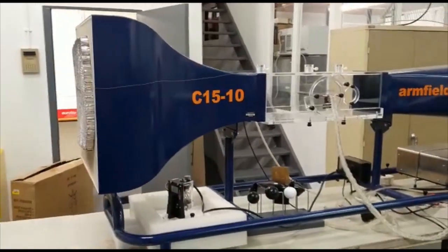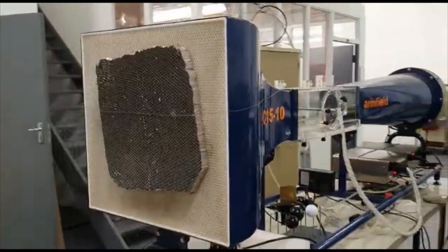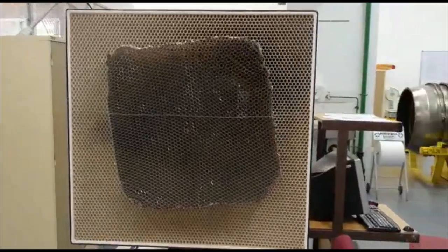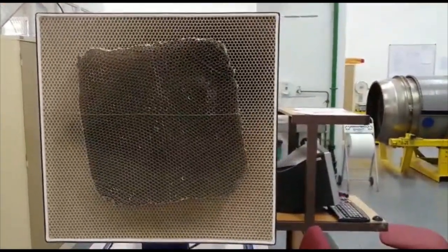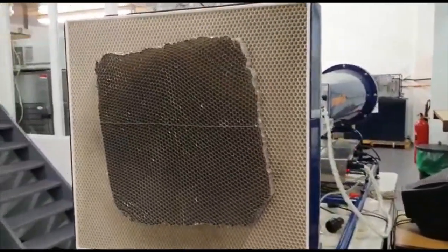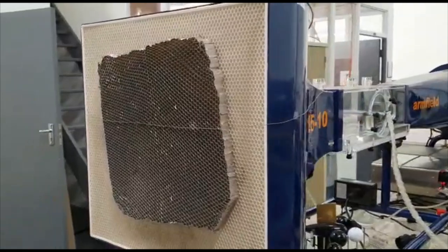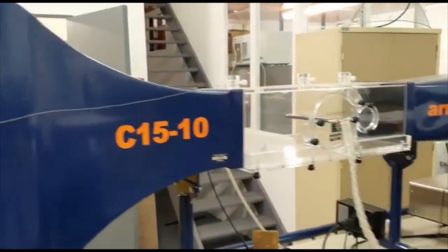So this is the wind tunnel that we are using, and I'm just going to go through a couple of parts of it. At the back here we have what is known as the honeycomb, and so air is sucked in through the wind tunnel from this side, and the honeycomb helps to straighten out the flow, so whatever is on the outside of this gets straightened out. It goes through the wind tunnel.